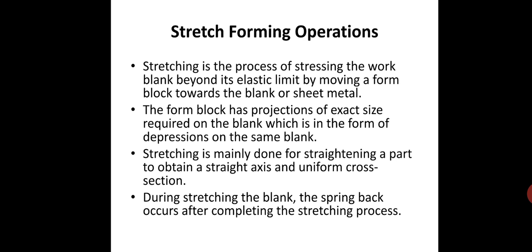Stretching is the process of stressing the work blank beyond its elastic limit by moving a form block towards the blank or sheet metal. This is the process of giving force to the blank beyond the elastic limit by moving the blocks towards the blank, that is the workpiece.